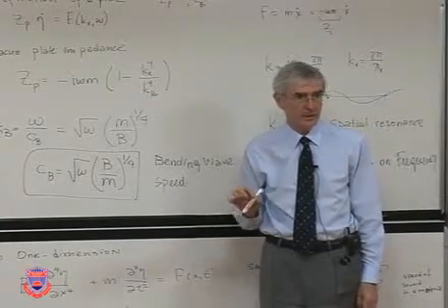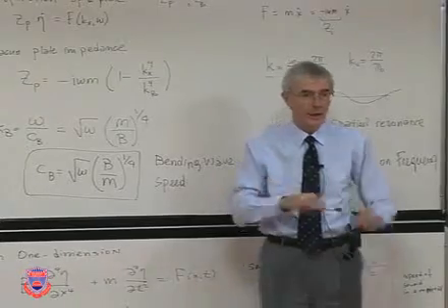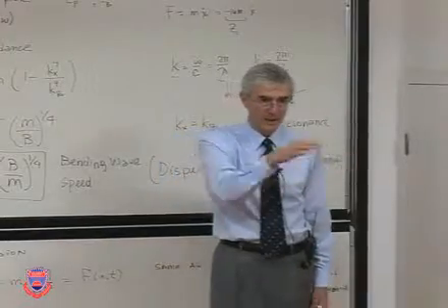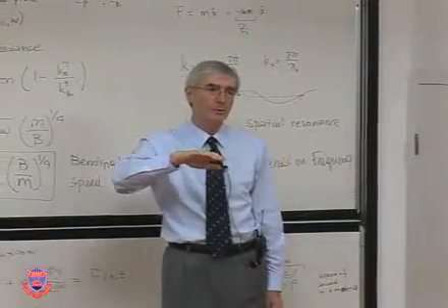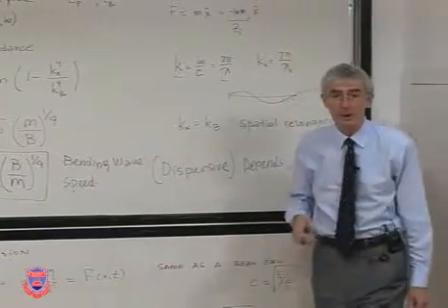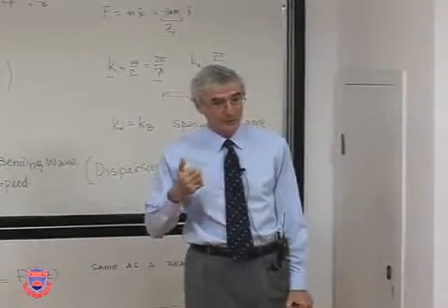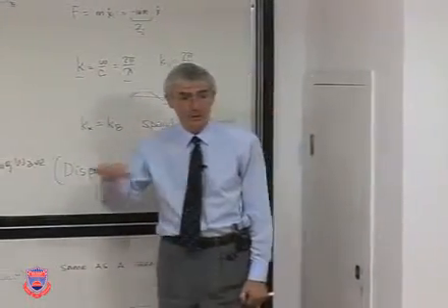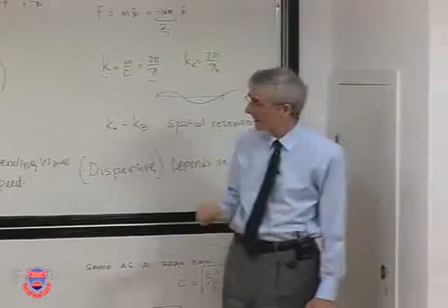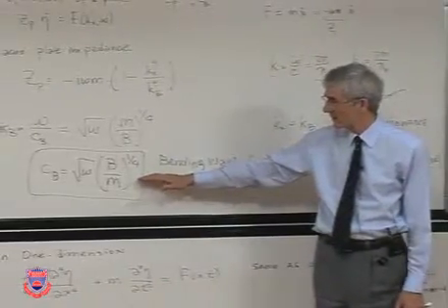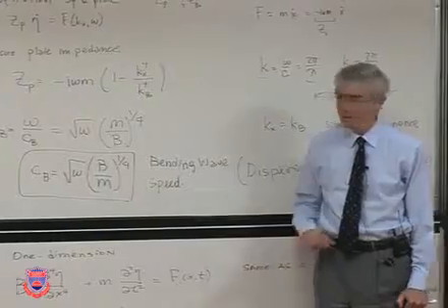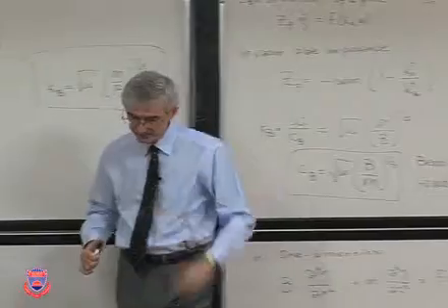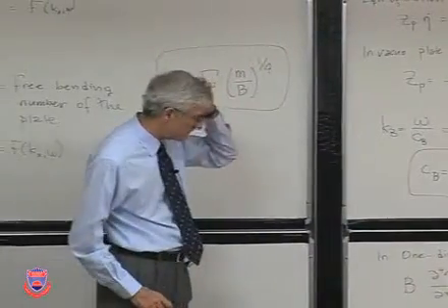This is very interesting and important. Why is that? We'll see in a moment. When a beam or a plate is vibrating, the waves have to travel faster than the speed of sound in air to be able to radiate. So only high frequencies radiate as much, rather than low frequencies, when a plate is vibrating. So this is a dispersive relationship that depends on the frequency of vibrations.